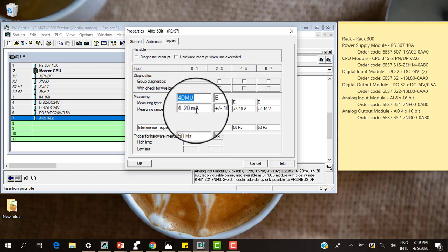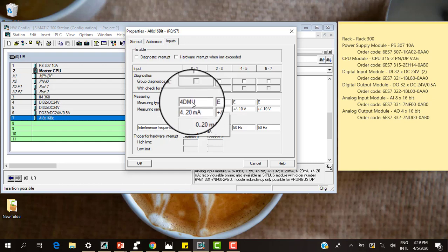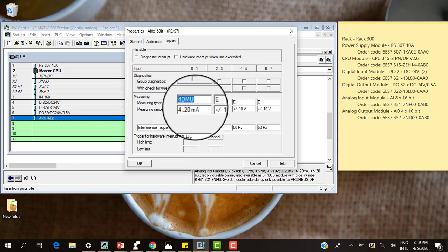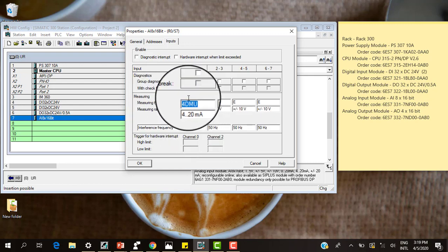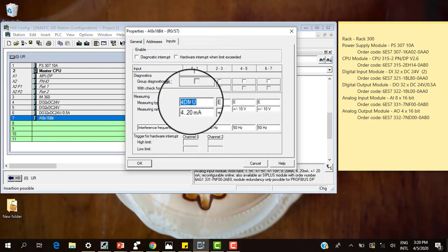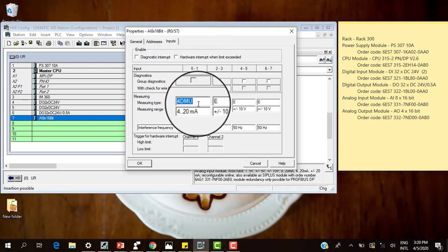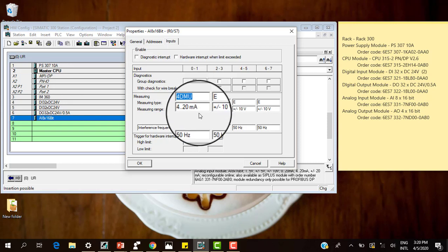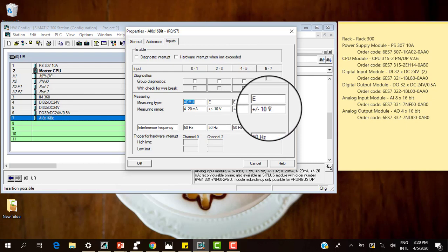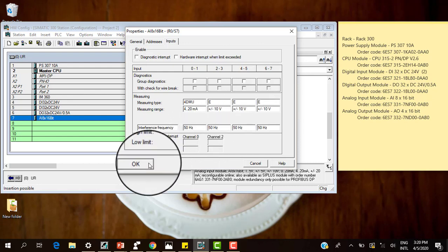In the case where you have a 4-wire transducer where your input sensor is giving you its value in milliamps, you then select current 4-wire here, and then you select the 4 to 20 milliamps. Physically, you need to configure this port to actually reflect a 4 to 20 milliamp input, and then you can select OK. You can do the remaining 4 inputs, and then just select OK.